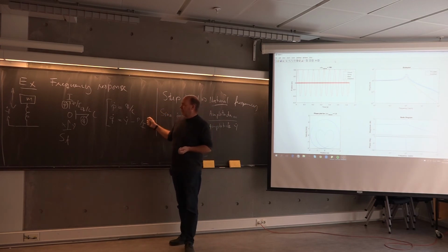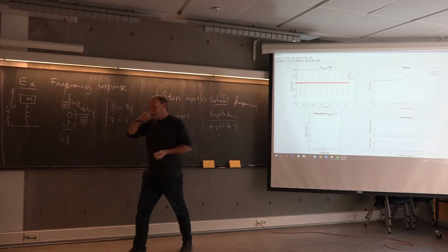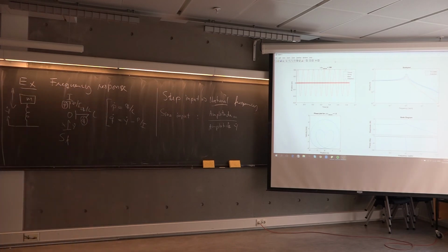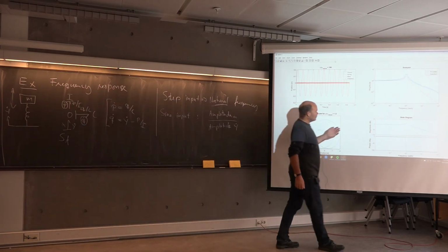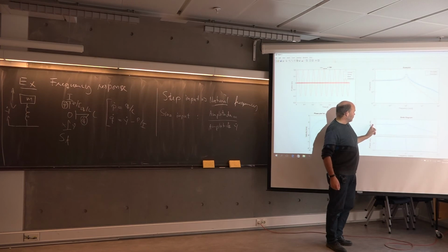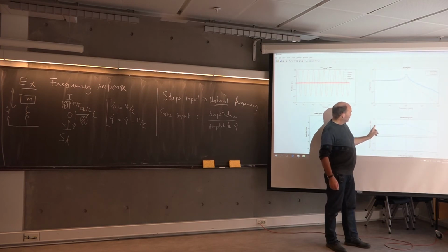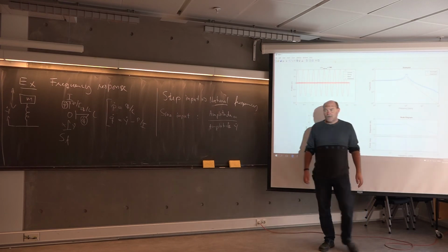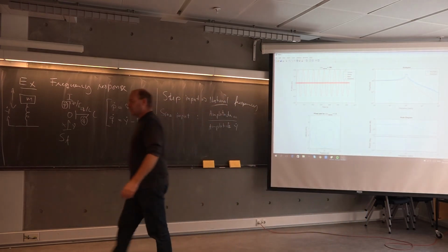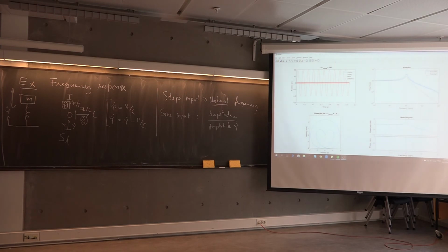You can create a second order differential equation, and then you can find what's called the Bode diagram directly to get this frequency response, the gain, the amplification factor, analytically. And you can do that in MATLAB. It's actually just one sentence or a couple of sentences in the code. I think I have it here.